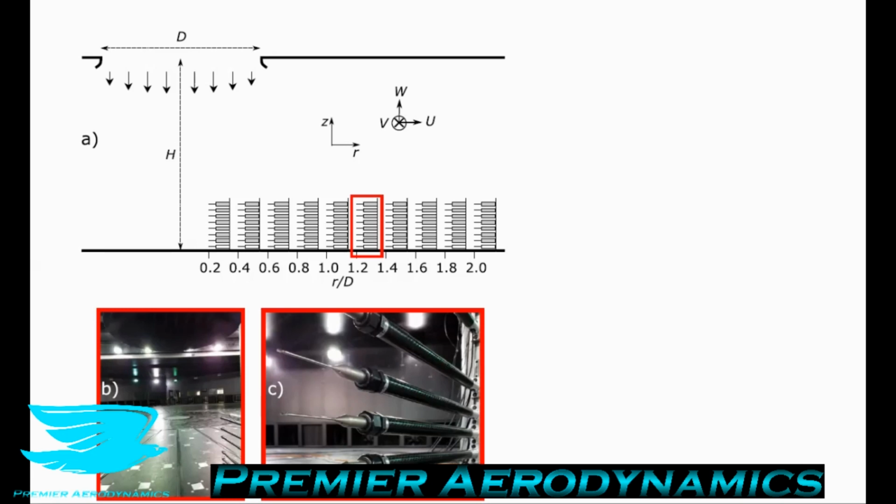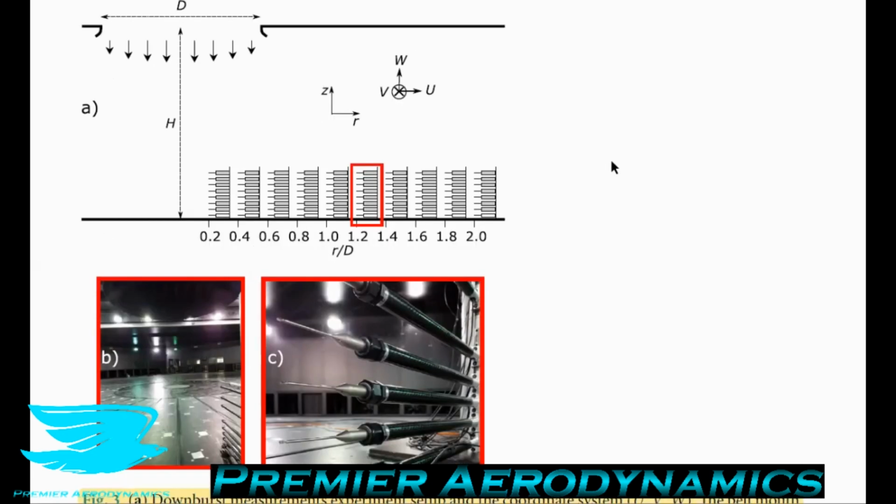So doing more measurements is good from that point of view. The downside of that is that you are using more resources. In this paper, the number of measurements they did were 2 jet velocities by 20 repetitions by 10 radial locations, so distance around the center, with 7 probes, resulting in 2,800 velocity records. So that's quite a lot. They're effectively doing a wake survey here with different probes.